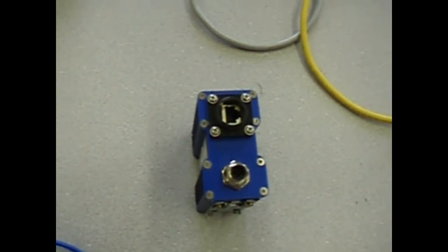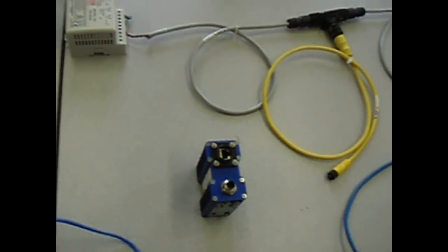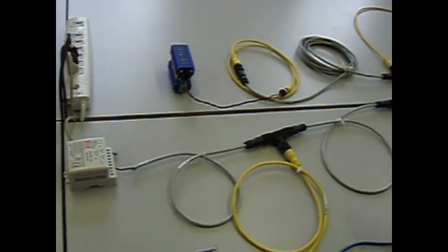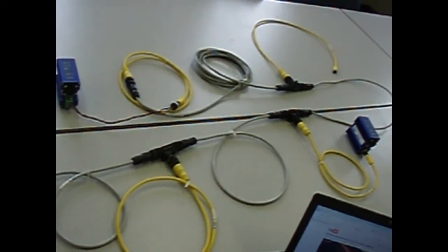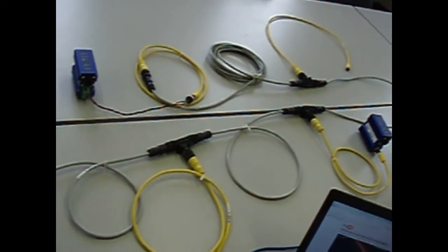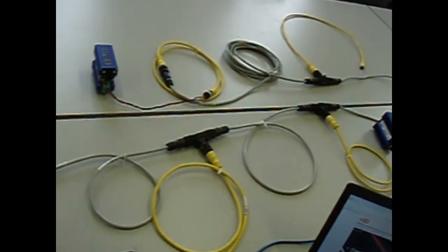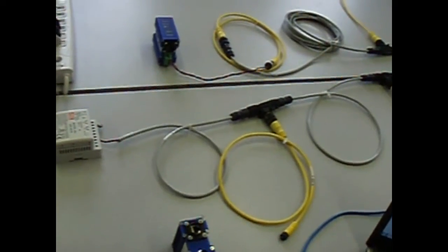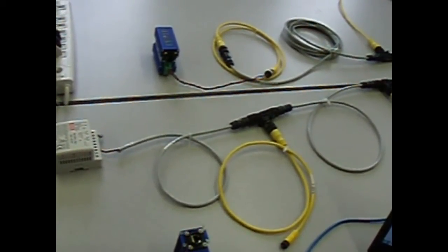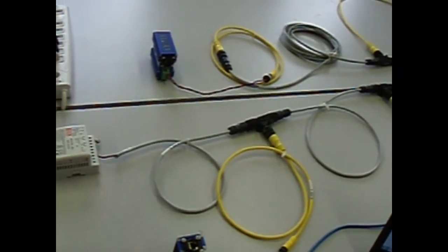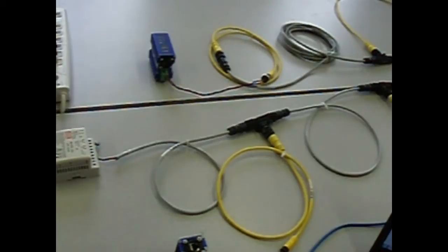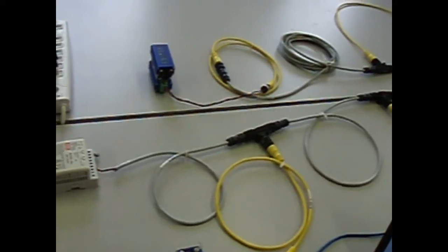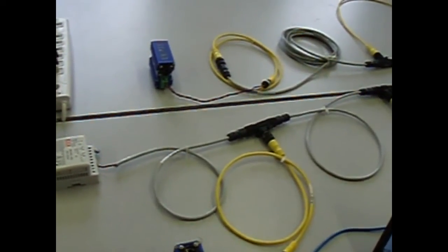The net bridge comes in a number of different types of terminals, thus connecting to cables previously used to carry Modbus Plus, Data Highway, Profibus, Genius IO, Interbus S, and many others. Many cables are disconnected and left unused as Ethernet replaces these older communication types. These are good quality cables and are already installed in the application. This technology will reuse those cables, some that may be as long as 1,000 feet, and thus can significantly reduce the cost of transitioning to Ethernet.